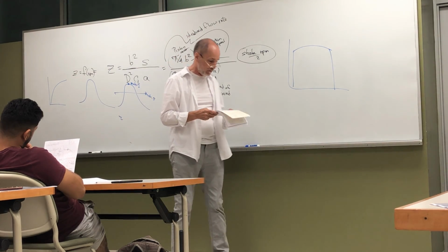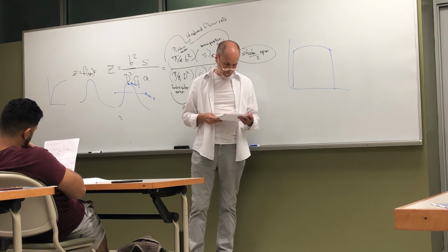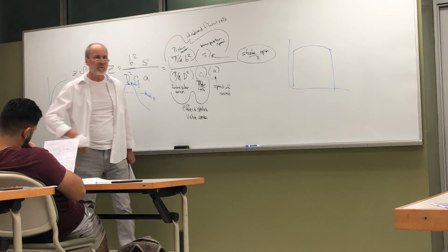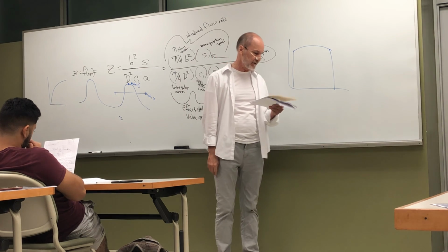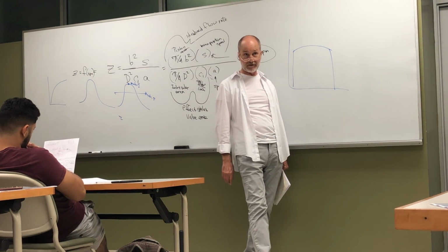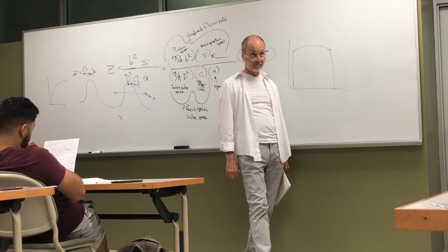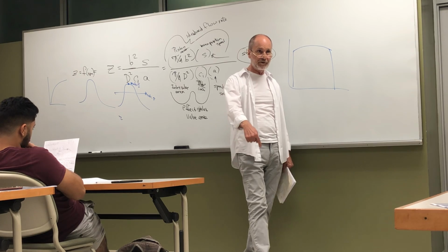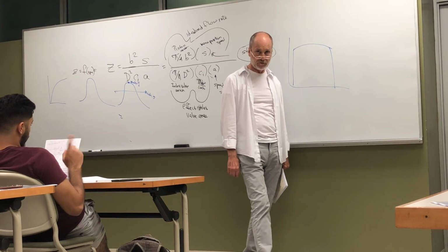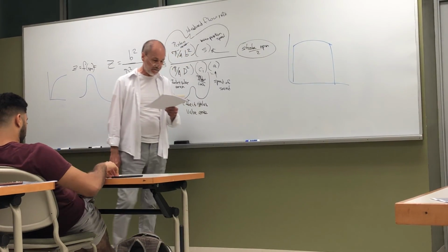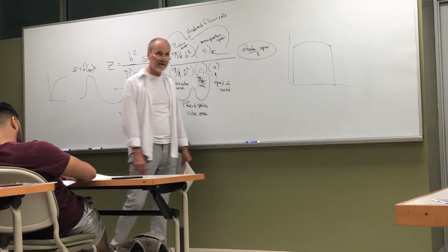Now, for intake manifold pressure 14.8 psi, what's that? Where was the gas pedal at intake manifold pressure 7.4? We've taken our foot off the gas, right? For intake manifold pressure 14.8, what do we do with our foot? All the way down, wide open throttle. For intake manifold pressure 22.1, what's happening?